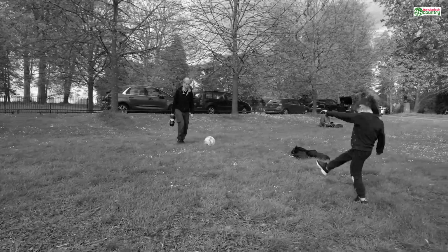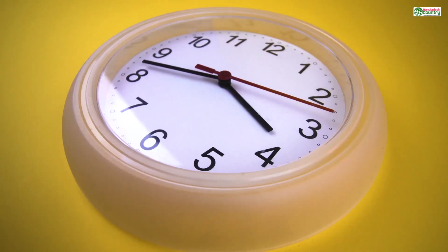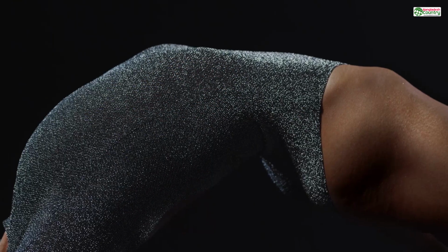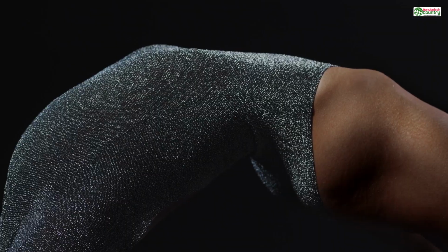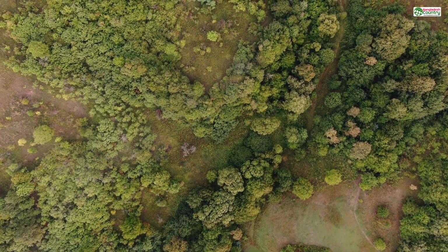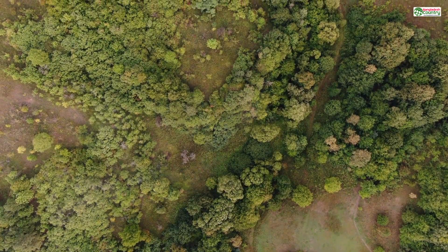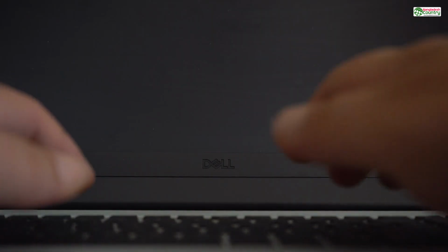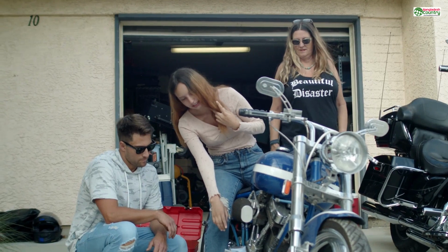The first and most obvious culprit is a literal hole, a missing face. This happens all the time, especially when you're combining different shapes or modifying an existing model. You might delete a section, and the software doesn't automatically patch the opening. It's a gaping wound in your model's geometry. To the computer, this isn't just an opening. It's a breakdown in logic. The very definition of a solid object is a continuous closed surface. A hole breaks that definition.